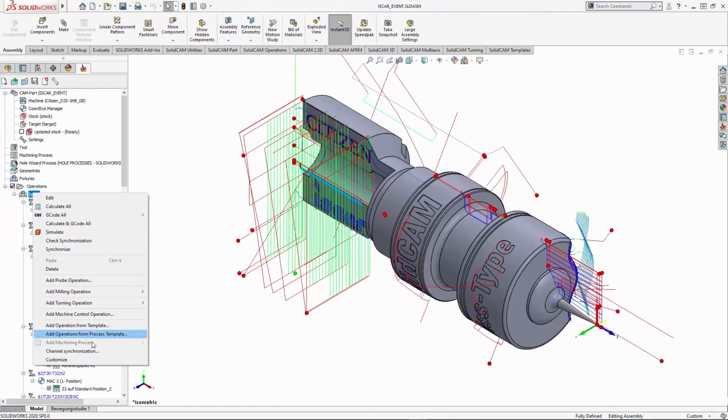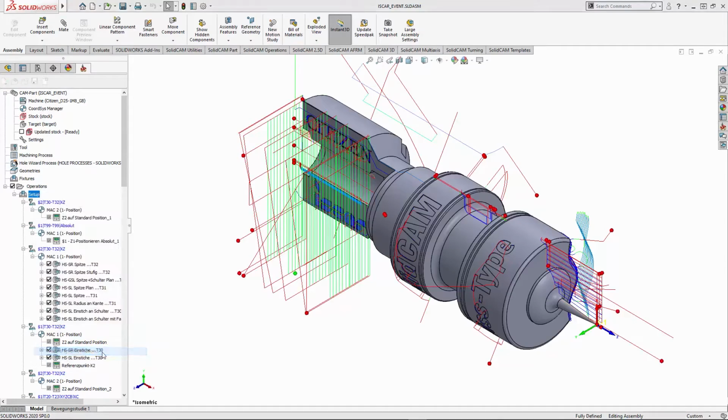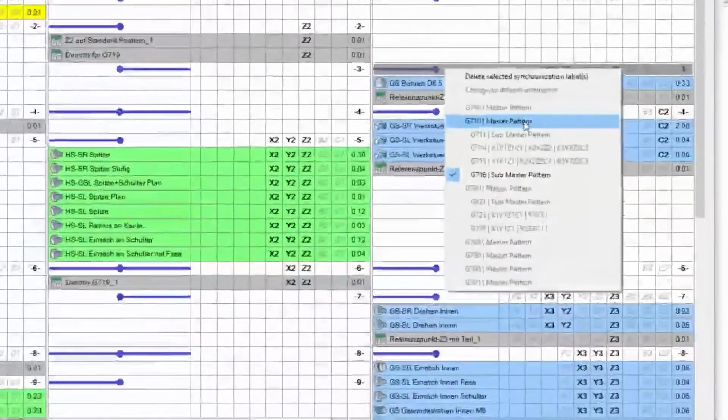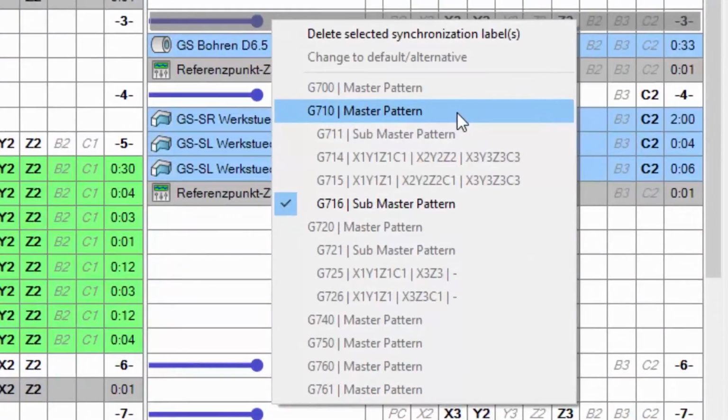And due to this, you can save setup times because you're setting up more frequently. If you're used to using SolidCAM, setting a Swiss type up is not much different to setting up a mill turn machine or a milling machine, and the software works in the same manner. So actually, setup times are vastly reduced on these type of machines, and again, it's consistency in the programming as well.